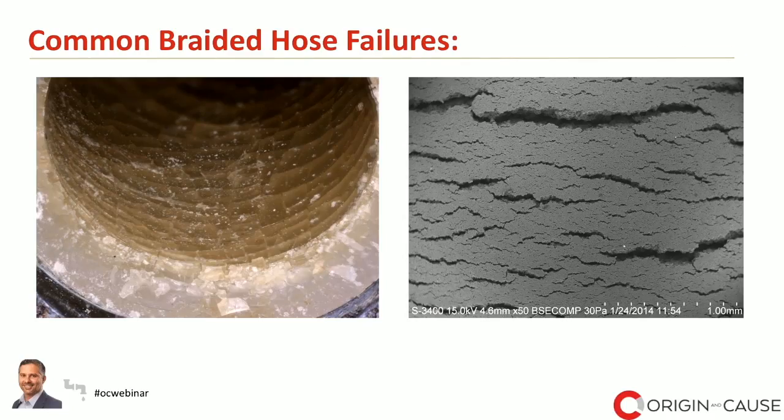So this is a close-up of the inner hose showing material degradation. You can see in the photos here cracks showing that the component has been degraded, and basically it just leaks from those cracks. So even if you can't see these cracks from the outside of the hose, failures deriving from material degradation of the hose can cause devastating damages and very expensive claims.